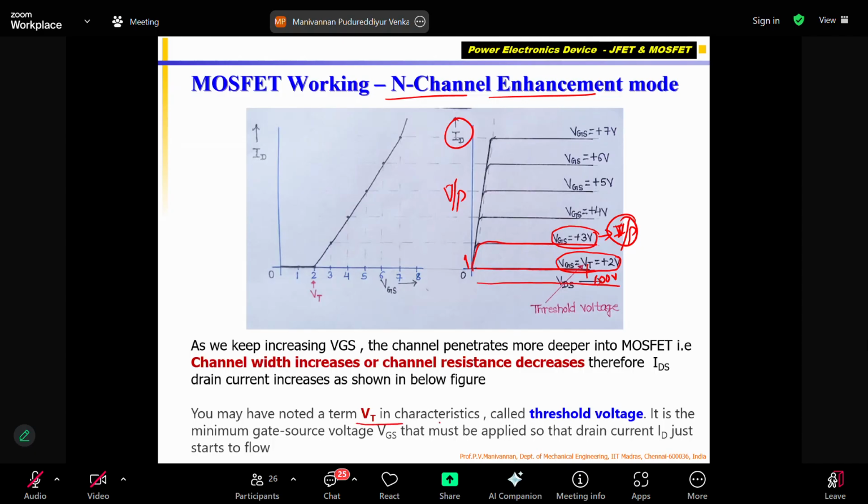Threshold voltage is very important. It is like VBE equal to 0.7 volts in the case of a transistor, and diode voltage 0.7, correct? That is called the cut-in voltage, correct? In the case of a transistor and a diode, it was called the cut-in voltage, which was VBE equal to 0.7 volts in a transistor, VD equal to 0.7 volts in a diode, for a silicon transistor made of silicon material.